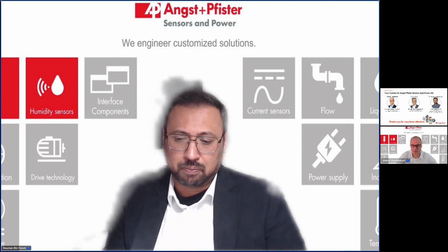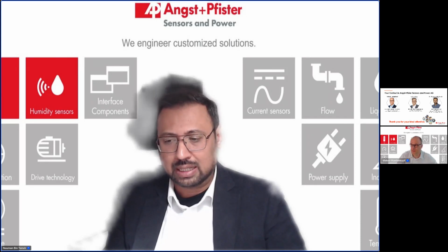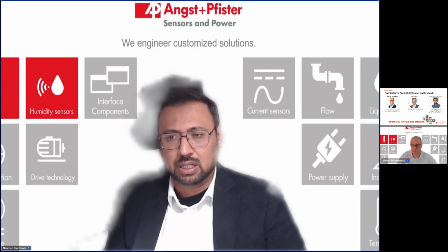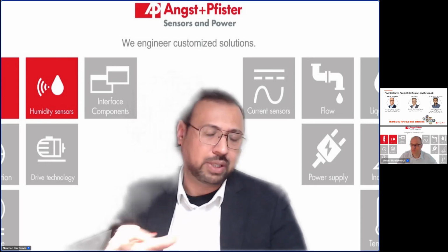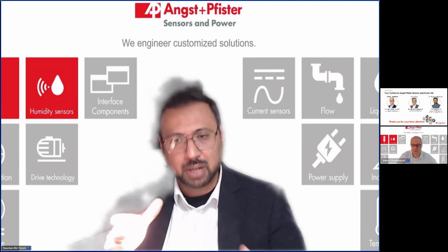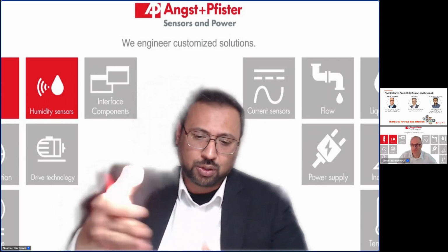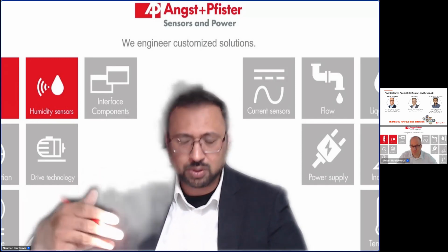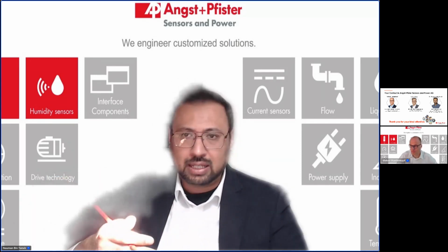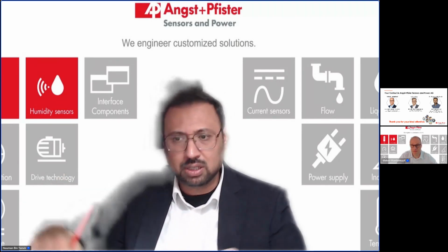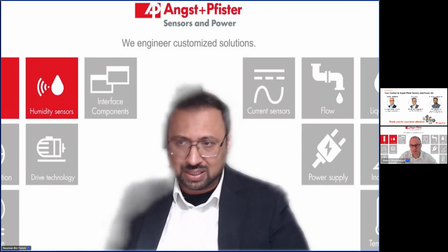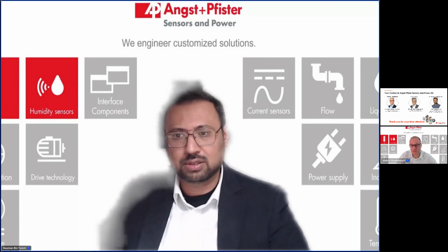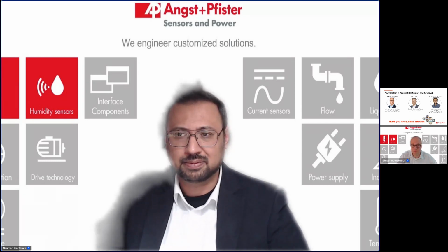However, the orientation in general can have an influence on the potentiometric and paramagnetic working principle, but it also depends on how we integrate it. For example, we can have a bypass solution, where we take the gas sample in, analyze it with the sensing technology, whatever we decide on, and then exhaust it back into the main process line. With this kind of approach, it doesn't matter what the orientation of the sensor is. It would, in any case, be working without any issues. Okay, thank you.